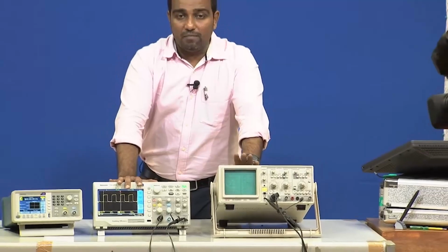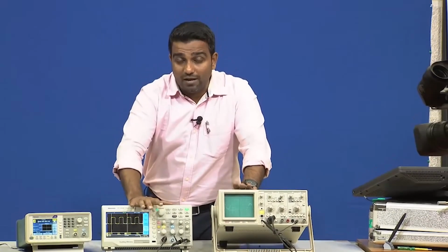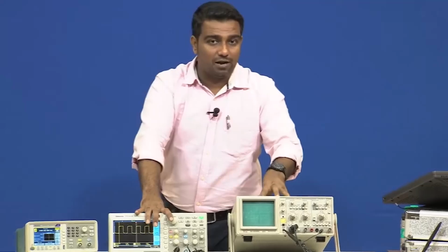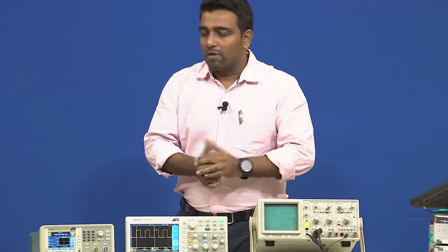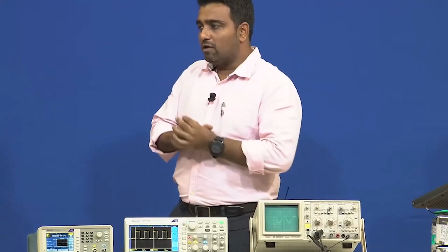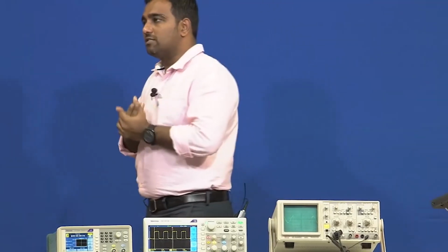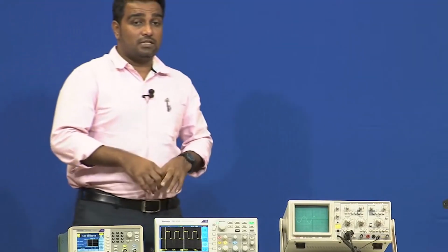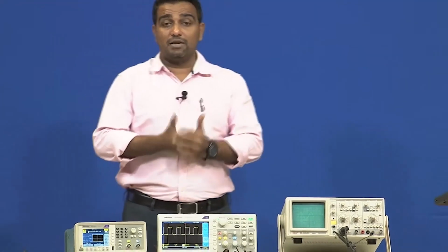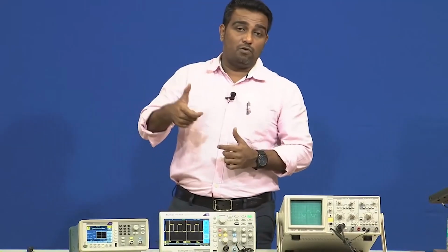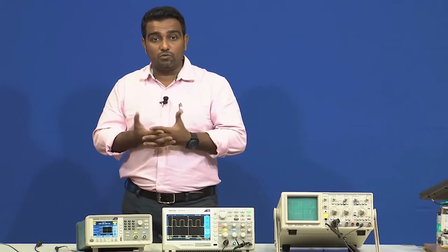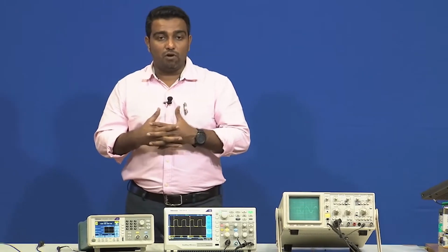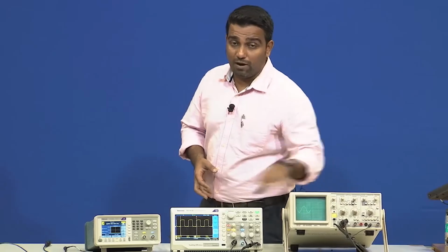Third, this is portable, easy, lightweight, this is not lightweight, right. If you want to just compare quickly, okay. But the final point is that oscilloscopes are used to measure the signal, and we can change the signal and see the change in the signal by measuring the time or the amplitude. You can change the peak to peak voltage, you can apply different filters to it, you can do math functions. Here you cannot do that, but here you can.